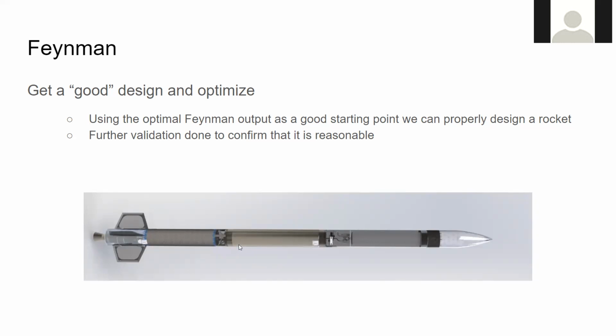Under cryogenic conditions, stainless steel actually gets stronger, and it's also a lot easier to weld than aluminum. Since we're welding and making our own tanks, anything that makes the process easier is a big win for us. And then we have our carbon fiber tank, which has an aluminum top and bottom ring so that we can clamp onto it.